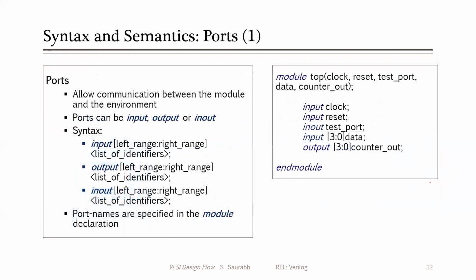Now, in a module you will have ports, as we saw in yesterday's class. In a module, you can define input ports and output ports, and also in-out ports in Verilog. If you have buses, for example a data bus or address bus, consisting of a group of signals, then you can define a range, a left range and right range.